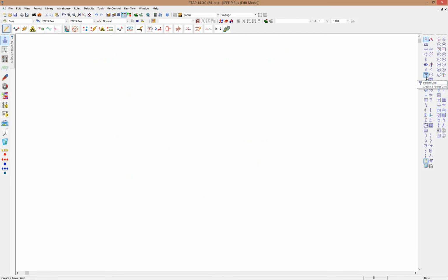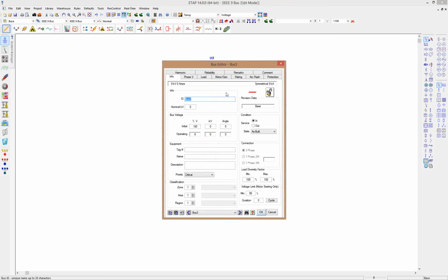Again, for those of you who are not familiar with ETAP, I can build a network model fairly quickly by just dragging and dropping and connecting components together. So I just have a very simple utility transformer, let's say another bus, and we'll go ahead and connect a machine to the system as well. You can simply double-click on the component to access the property editor.